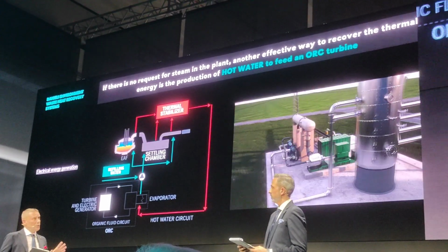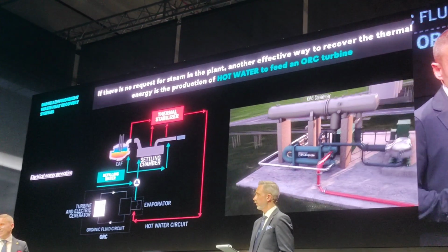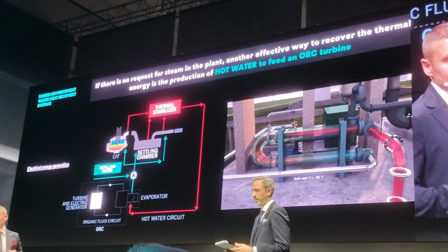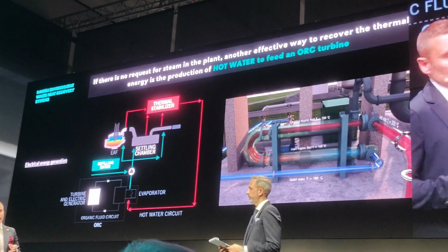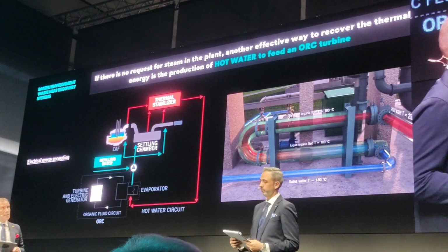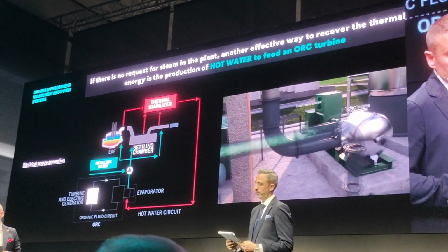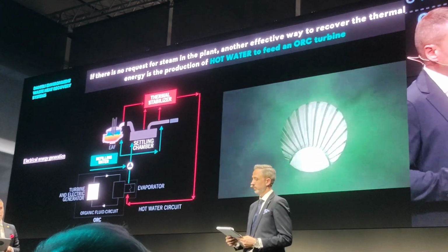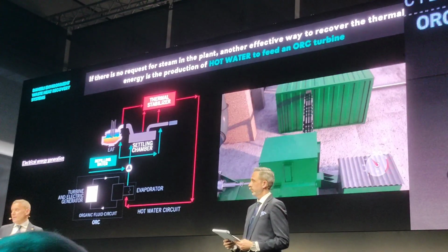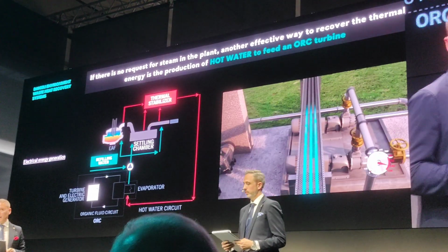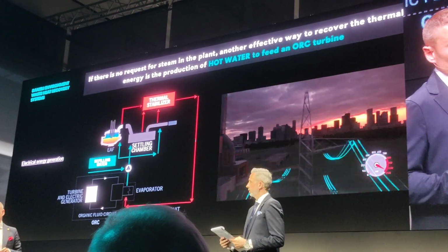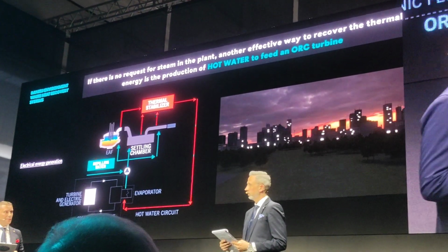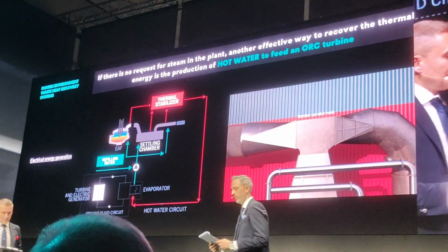And now the stabilized water is introduced inside the ORC evaporator, where the organic fluid evaporates and, passing through a turbine, generates electrical energy. This is a plant that has a production of 1 megawatt of electrical energy, since it refers to the organic Rankine cycle system installed in an ABS plant, and it has worked for around 5-6 years. Okay, thank you, Manolo.